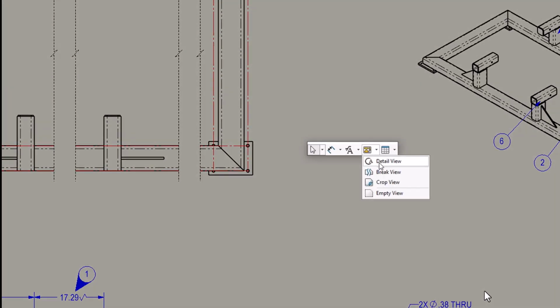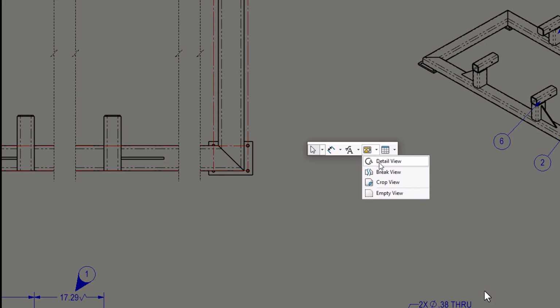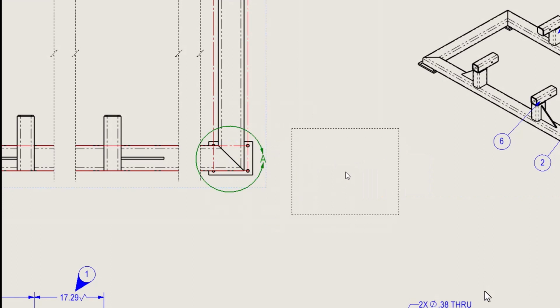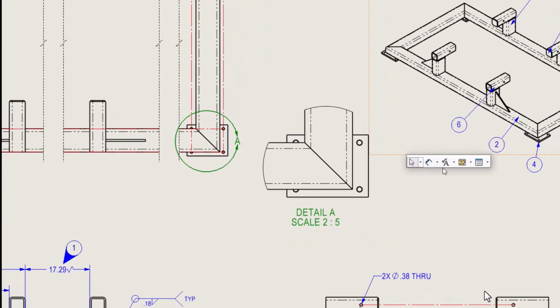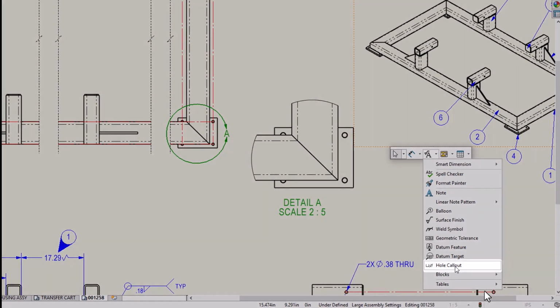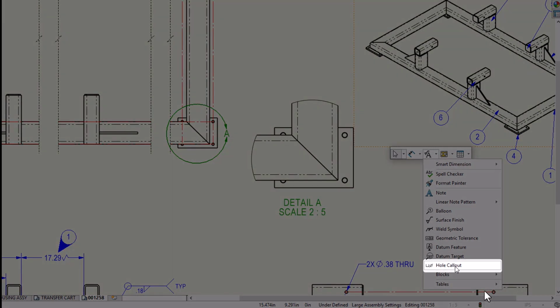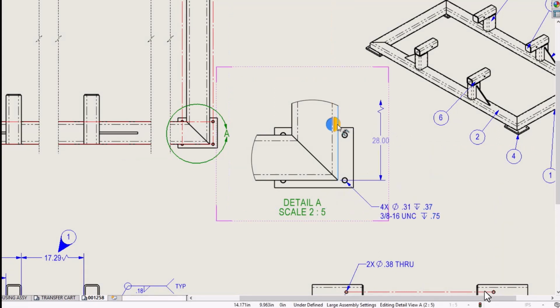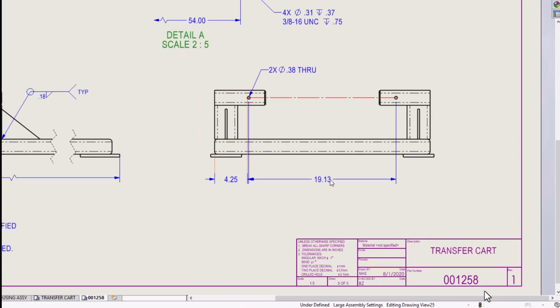Detail views can now be created in the same manner as we would when the drawing is fully resolved. Just draw the detail circle or choose a sketch profile and place the view. When detailing drawings, it's common to define hole information, and starting in SOLIDWORKS 2021, Detailing Mode supports hole callouts. And foreshortened dimensions can be applied when necessary. Existing dimensions have full editing capabilities.